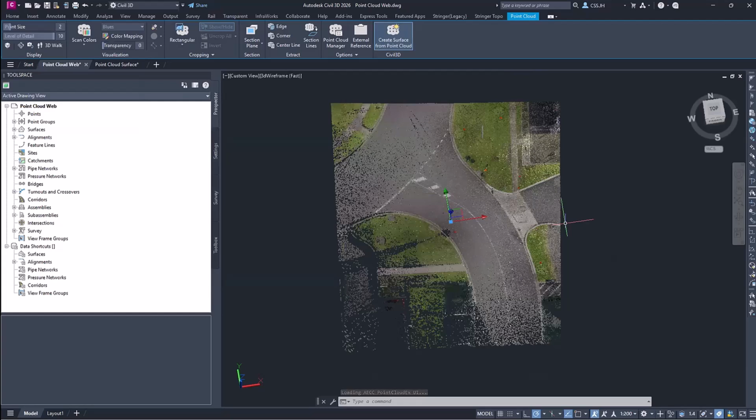However, I will state if you make any edits to your point cloud, things like cropping and such, be aware that this can cancel the surface creation. You will get a message saying that it has been cancelled, but it can happen if you edit the point cloud in such a direct way. Things such as changing the scan colors, creating new points, all that, you're completely fine. It's more the removal or editing of an already existing point cloud. So you just keep that in mind.